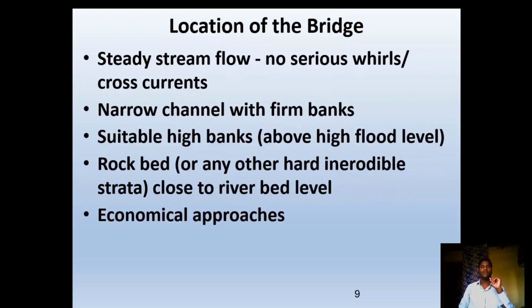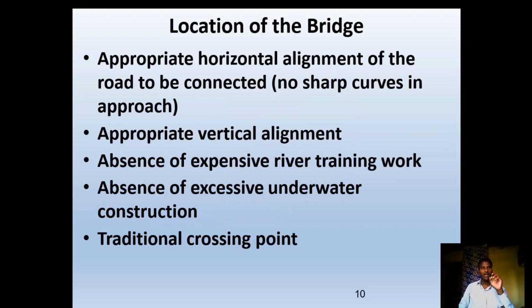Then location of bridge, another important aspect. Steady stream flow, no serious eddies or cross currents, then a narrow channel with firm banks, suitable high banks above high flood level, rock bed or any other hard inerodible strata close to river bed level, economical approaches, then appropriate horizontal alignment of the road to be connected.